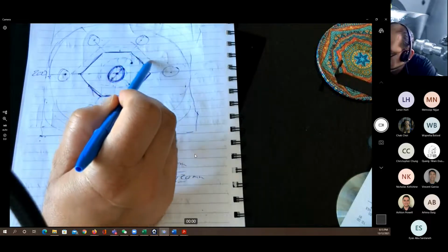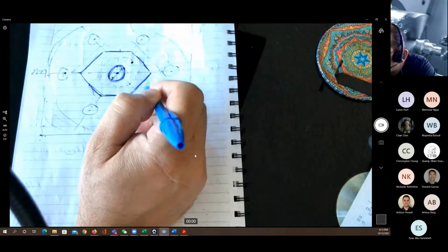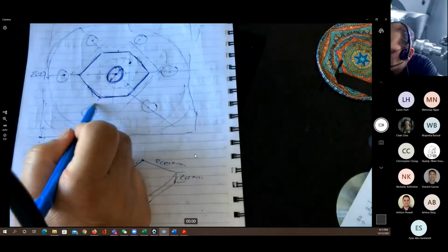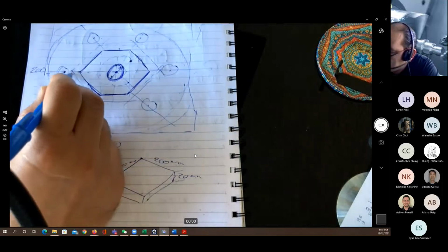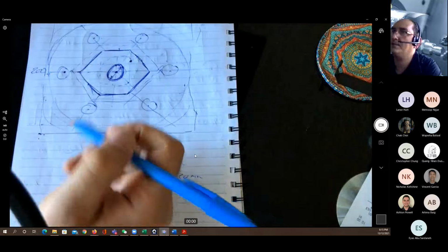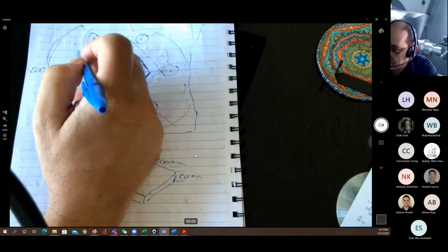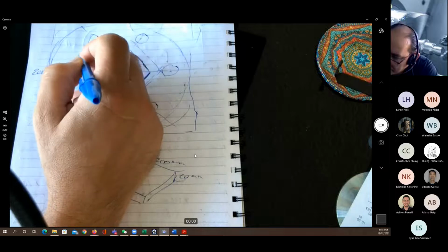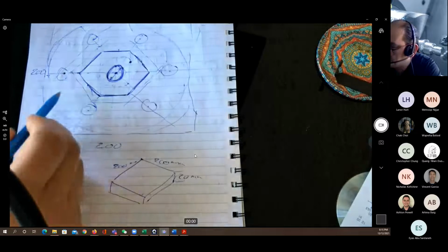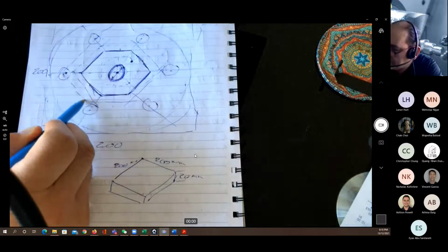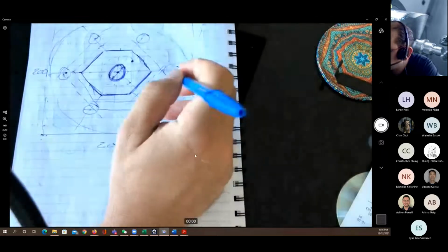You can see obviously that these lines are going to be intersecting with each other on the axis of the hexagonal shape. This will be one cut. Now, offset this line by another 6 millimeters. And once again, just remember that we always need to extend these lines so they're going to have some intersections.